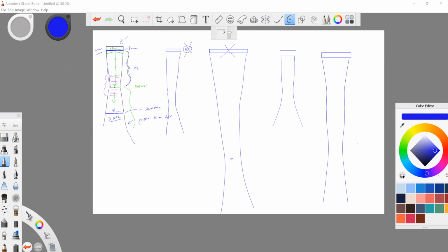The point being, anytime that you bring the focus closer, the far field spreads out faster. Anytime you bring the focus deeper, the far field spreads out slower, not as fast a spread. So, wide aperture, high frequency is going to have the least amount of spread, and that's a good thing if you're trying to image the far field. Small diameter, small aperture, low frequency is going to have the most spread in the far field. And so that's not helpful.